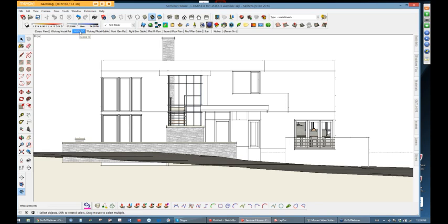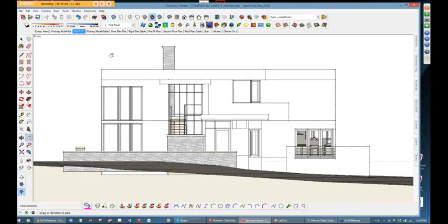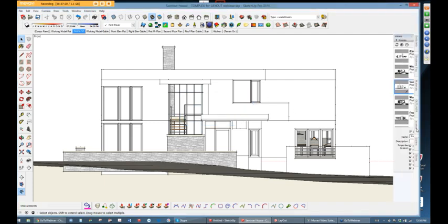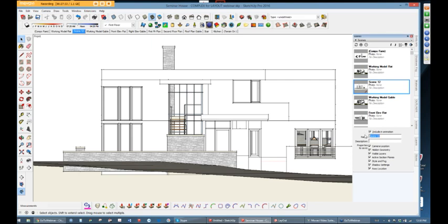And then just update this scene. And I'm going to pan this down a little bit. And it doesn't really matter where on the screen you will have this, because in layout you're actually going to have a viewport that you can tighten up on this drawing, get it down to exactly how much you want to show. Right click on this and I'm going to pick update. Now in scenes, a good idea here, especially if you're exporting to layout, is name these scenes. So I'm going to call this front elevation. I already have one, so I'm going to call this 2. Just to keep things clean.